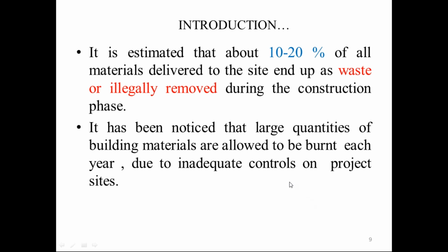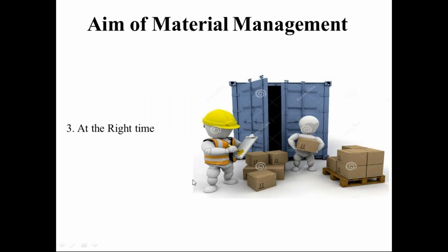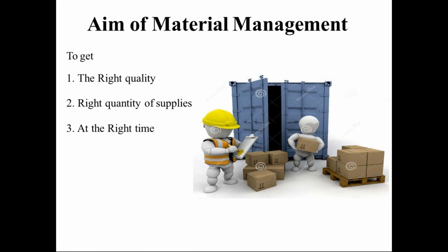It is estimated that about 10 to 20% of all the materials delivered to the site end up as waste or illegally removed during the construction phase. It has been noticed that large quantities of the building materials are allowed to be burned each year due to inadequate controls on the project sites. So the aim of material management is to get the right quality, with the right quantity of supplies, at the right time, at the right place, and for the right cost.